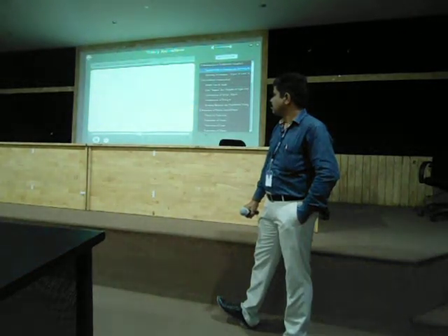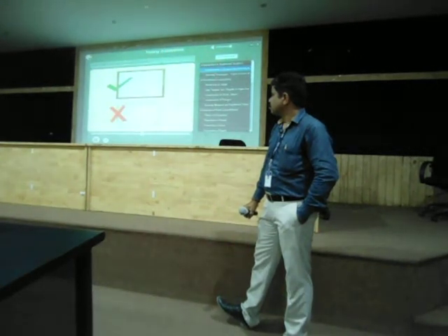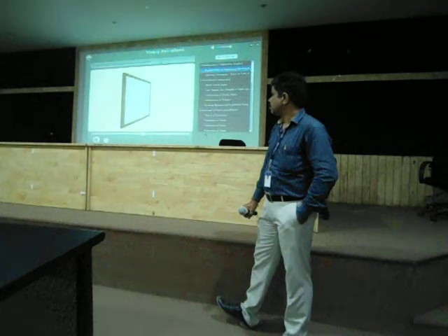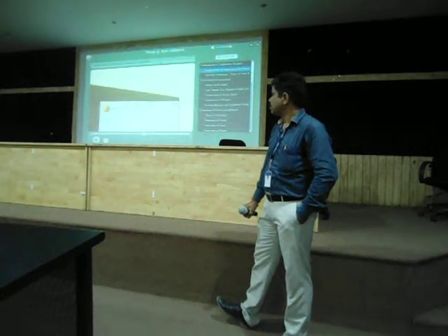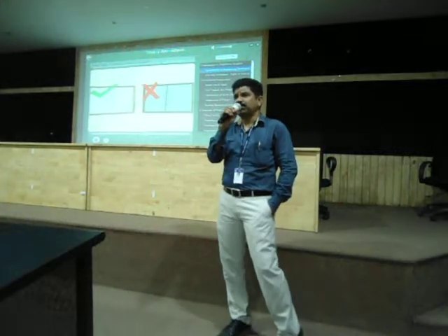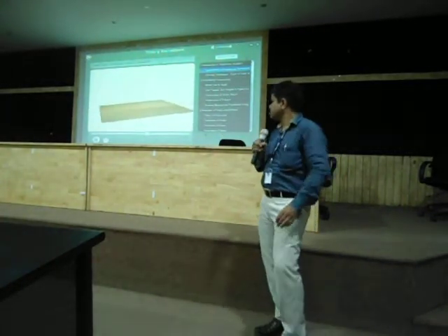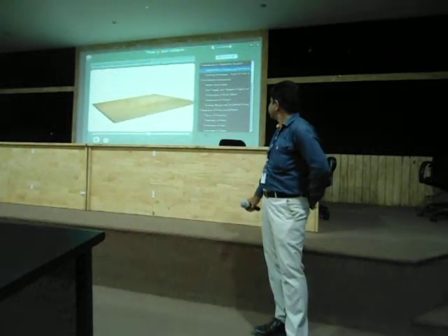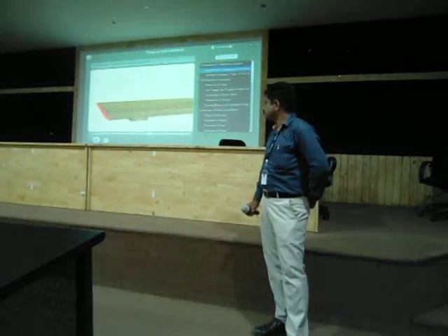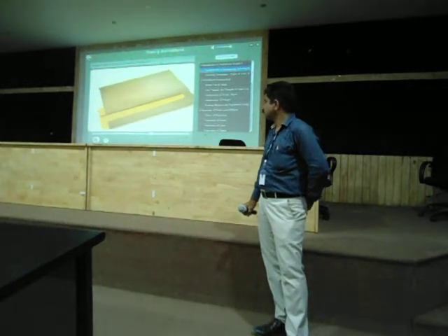Before you start drawing, always make sure that the size of drawing paper is less than the size of the drawing board. Also make sure that paper is fixed properly with drawing pins and it is smooth without any wrinkles. Instead of pins, we can use clips. The drawing board is a plain and smooth surface used for drawing purpose. The ergonomic edge of the drawing board facilitates smooth movement of T-square.